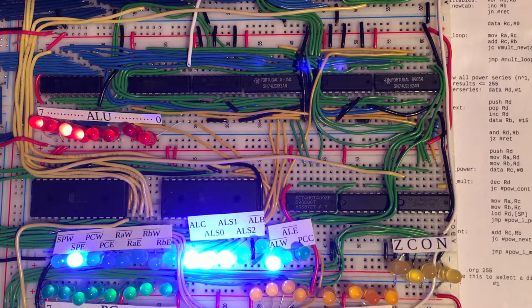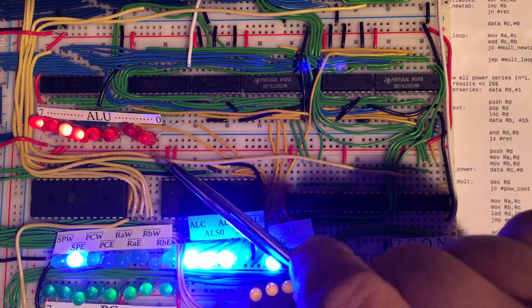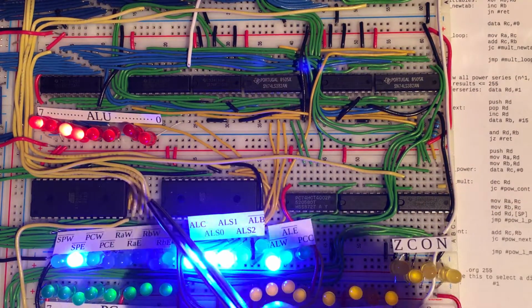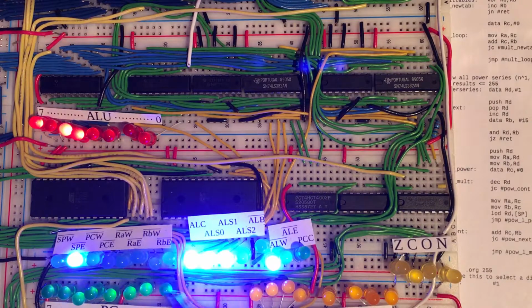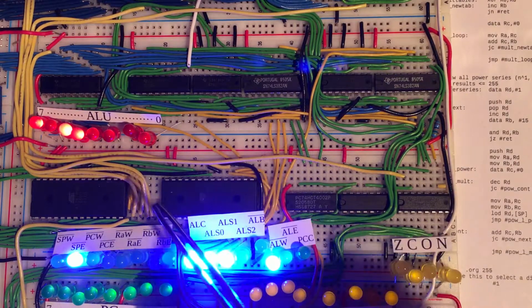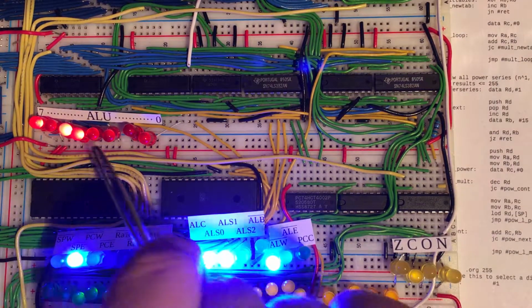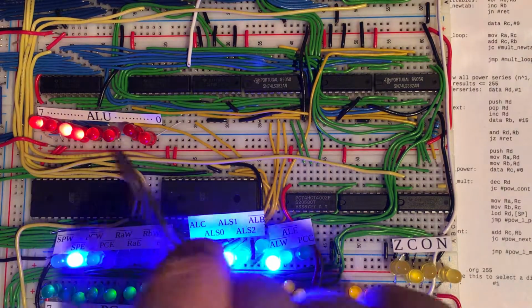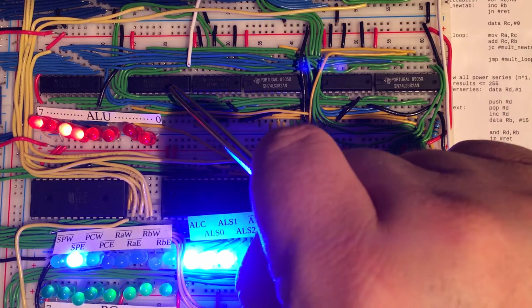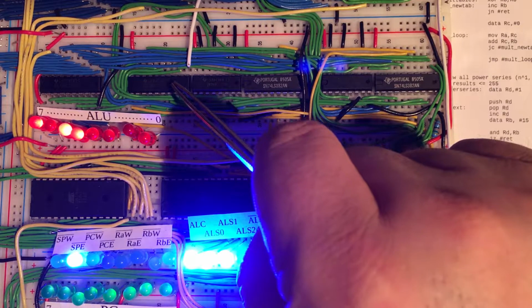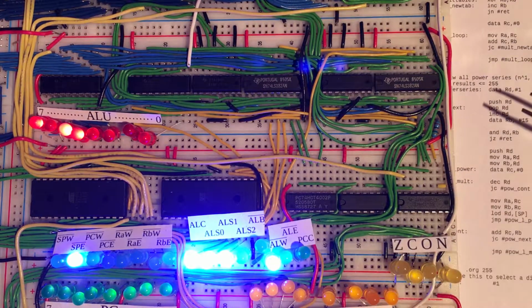So here is a view of that ALU in the hardware, and we can start recognizing some of the components. So the register, which the control logic periodically tells the ALU to write the result of its computation into, is being shown on these LEDs, and the actual register chip is here, and that's the 74HCT377, which we know very well and have been using quite often in this computer.